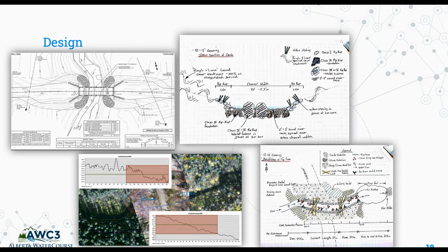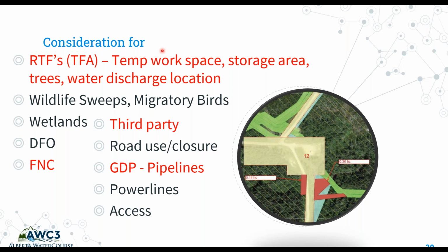Considerations in your planning or preparing for a site is temp workspaces. So if you've got a large, complicated site that you require workspace outside your right-of-way, you may require a TFA, or now called RTFs. You may require storage areas if you've got a large excavation, to remove some of the material from the site, or a bridge laydown yard, or your aggregate delivery. You may want to collect trees for your restoration program, and you also want to think about water discharge locations. All this will require approval, and it may also require First Nations consultation if you're over 0.5 hectares.